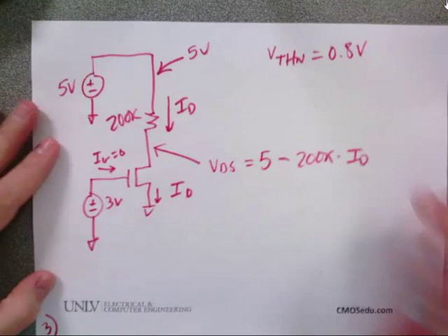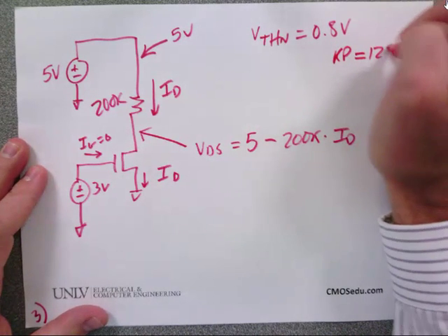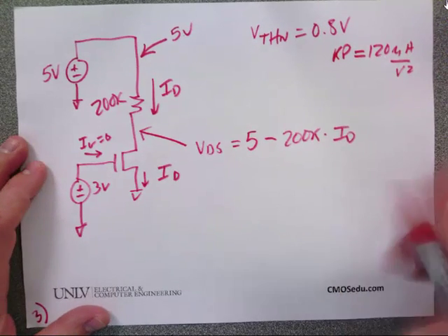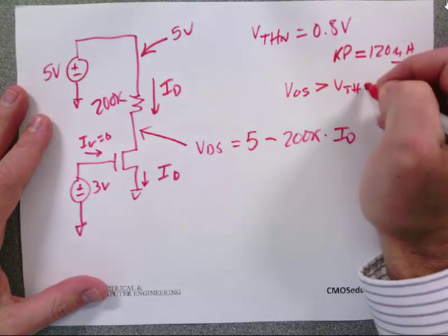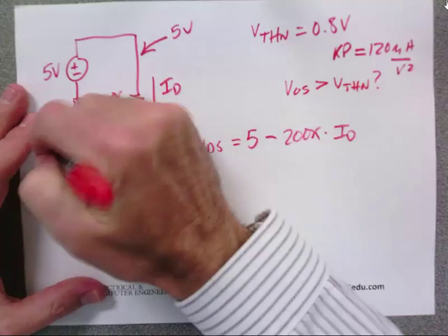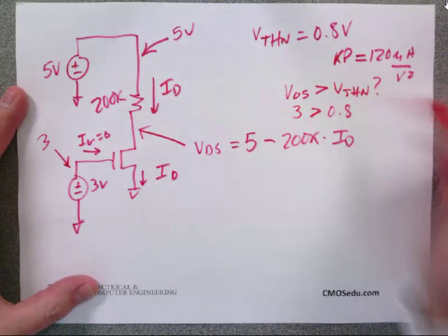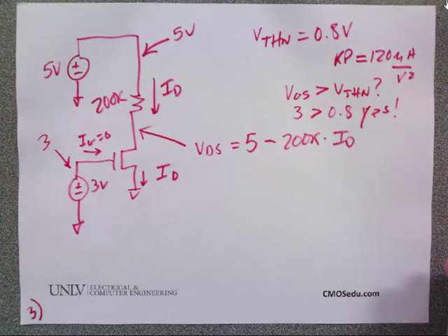All right. So here's where this gets kind of challenging. First thing I need to ensure for either equation is VGS greater than the threshold voltage. What is VGS again? 3. Is 3 greater than 0.8? What does that mean? Means there's current flowing. Doesn't mean saturation, doesn't mean triode. It means the water's flowing in the pipe. That's what turning it on past the threshold voltage is.